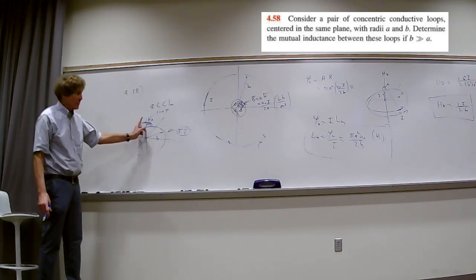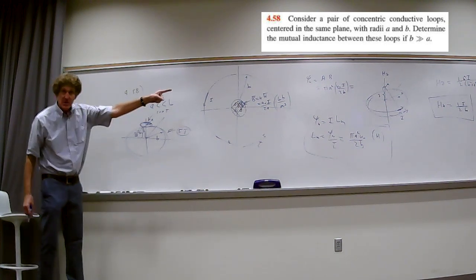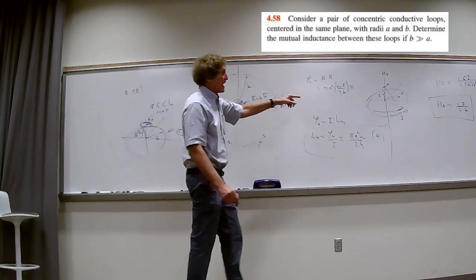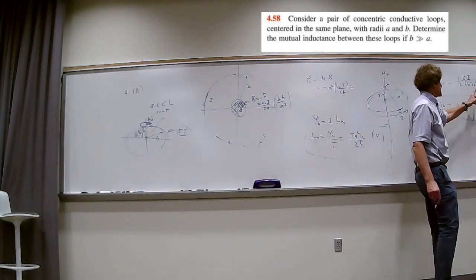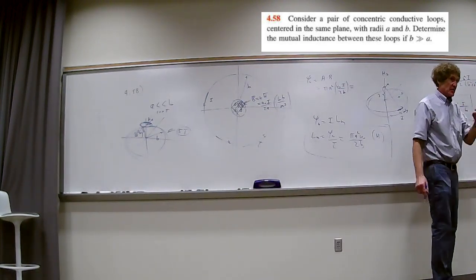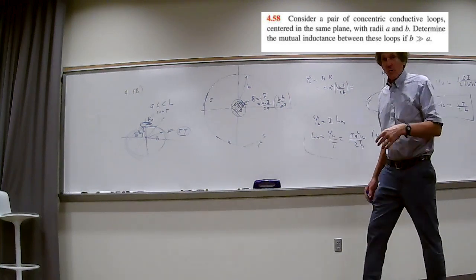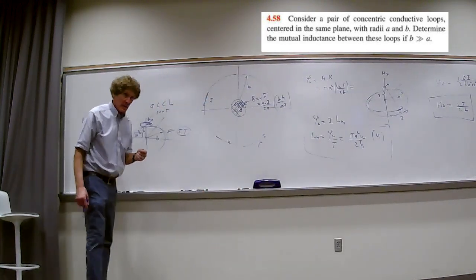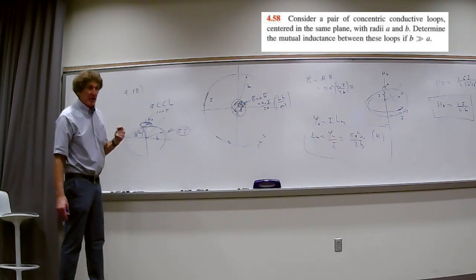The normal B field, which you can get from that equation, because you'll notice that's in the Z direction. Do you follow me? But now you would have to include Z. It's not 0. Then, once you found that H field, you'd multiply it by the area to get the flux.